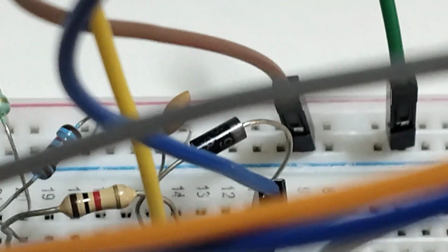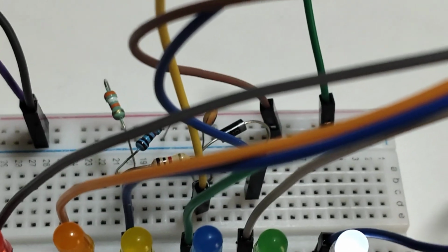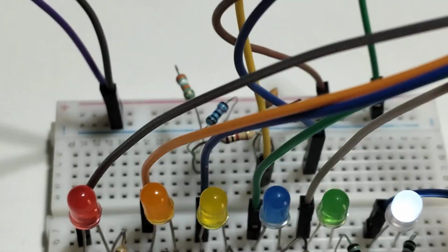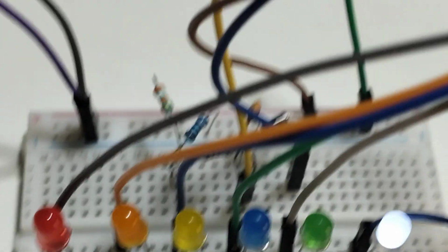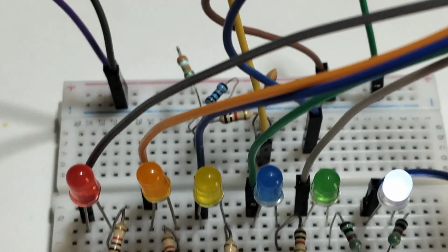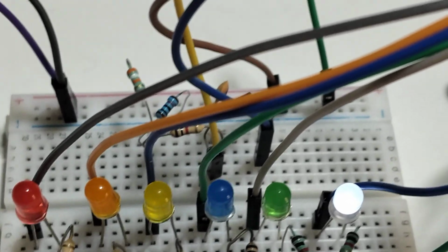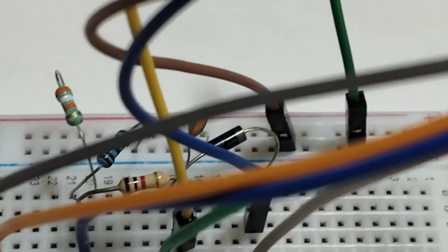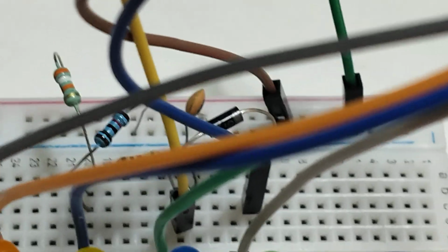And additionally, you can see that there's a diode, basically a Schottky diode, and it's a clamping diode, just in case there's some kind of over-voltage event, which shouldn't happen, but for safety, it will clamp the voltage at the ADC, because if it goes above 5 volts somehow, it's going to destroy the ADC pin, right? So this will clamp it, and it's placed between the ADC pin and the VCC pin, which is at 3.3 volts. So that is there.